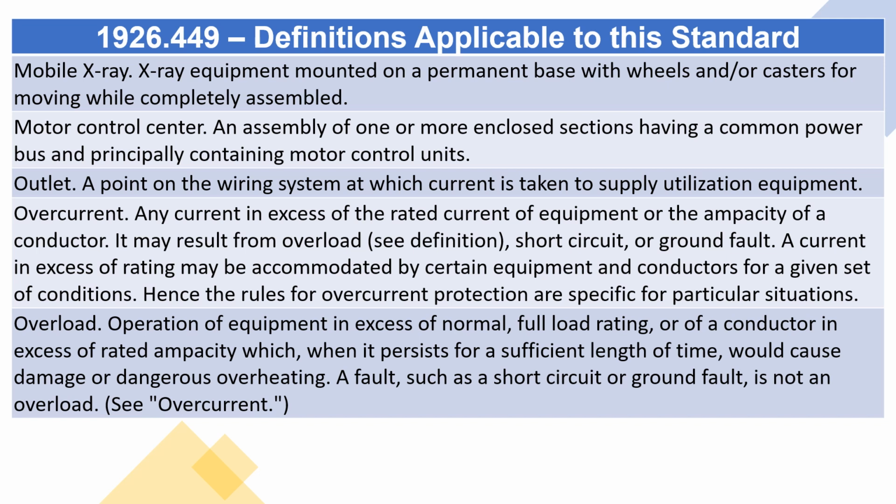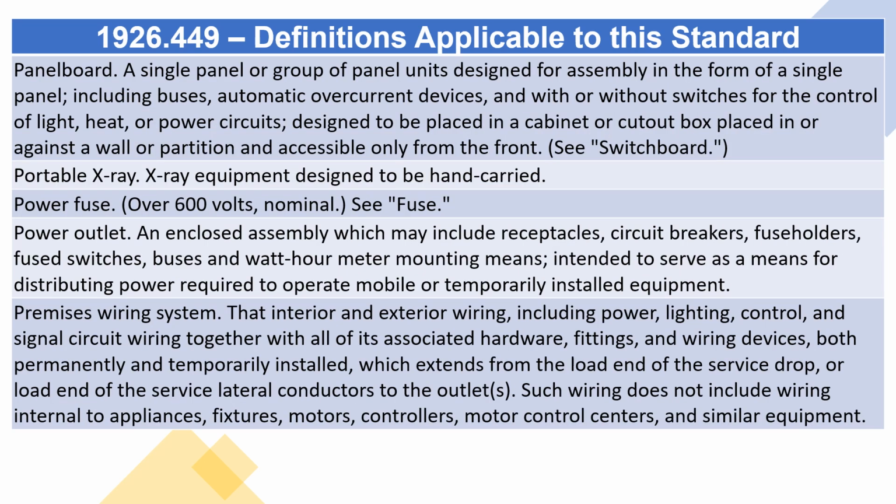Overload. Operation of equipment in excess of normal, full load rating, or of a conductor in excess of rated ampacity which, when it persists for a sufficient length of time, would cause damage or dangerous overheating. A fault, such as a short circuit or ground fault, is not an overload. See overcurrent.